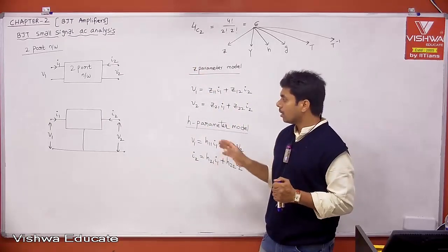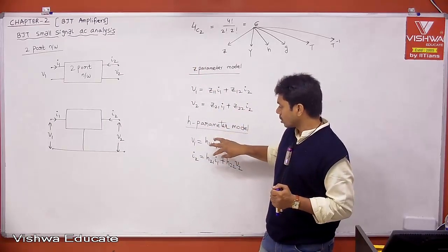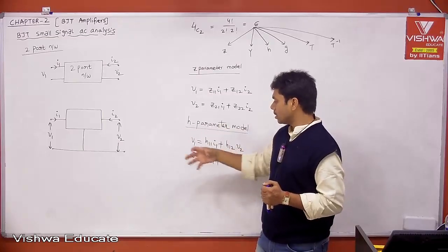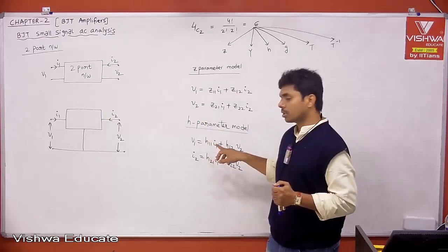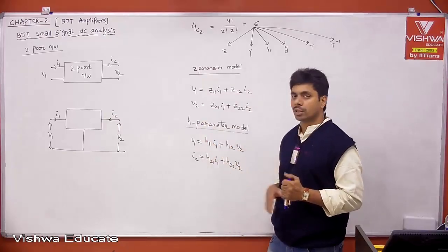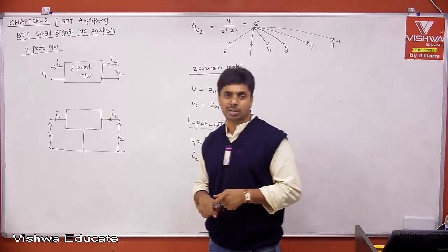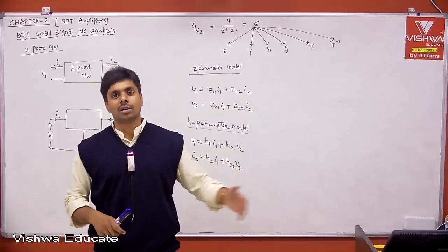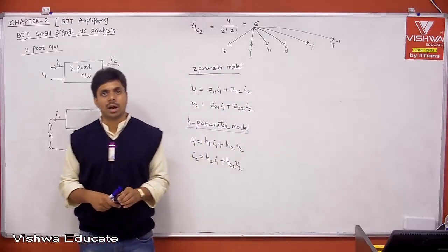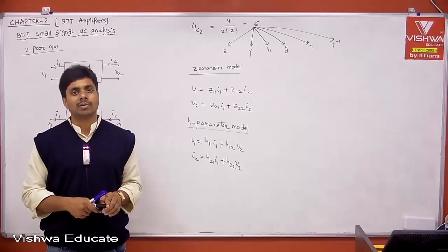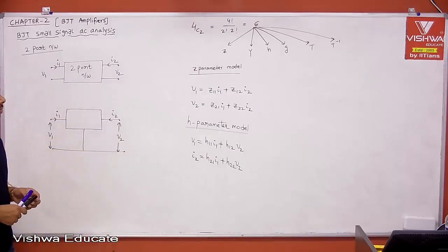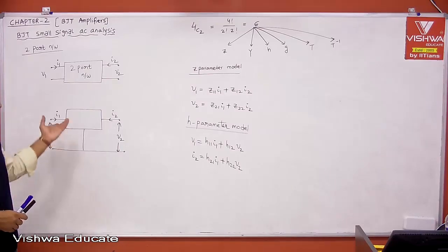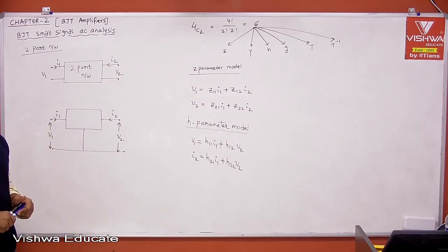Okay, write down. Later on, let us use these equations to convert them into an equivalent circuit, and let's replace the black box with the equivalent circuit represented by the equations. That is what is called the BJT H parameter model, which we use later on to solve all the problems, or to derive all the formulae. Okay, write this. Then let us change the subscripts to meaningful ones. Then we can continue. We can replace the black box with the H parameter model. Take it.